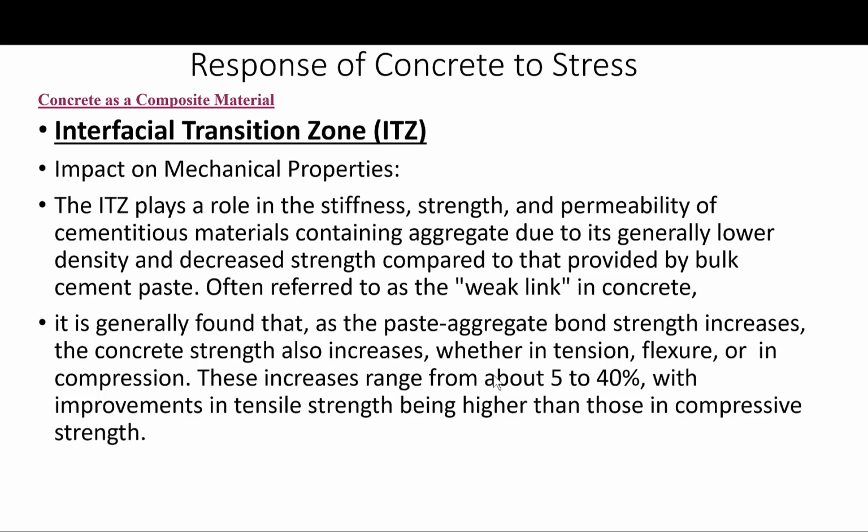However, it is generally found that as the paste aggregate bond strength increases, the concrete strength also increases, whether in tension, flexure, or even in compression. These increases range from about 5 to 40%, with improvements in tensile strength actually being higher than those in compressive strength.